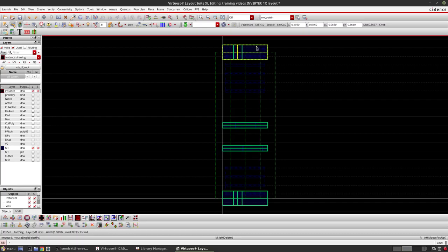mask 2, and the thickness of VDD and VSS is 80 nanometer. The width of M1, metal 1 horizontal strips, will be 32 nanometer, all the routing tracks in between except VDD and VSS which are 80 nanometer. Once that is done, you will draw PR boundary like this.